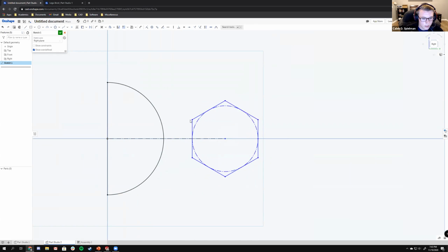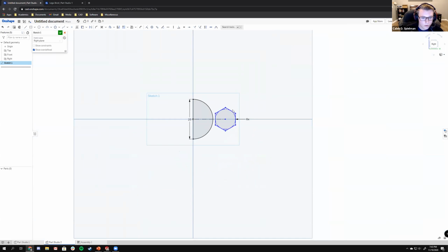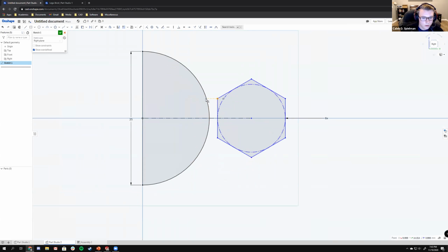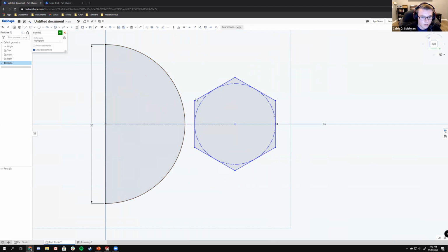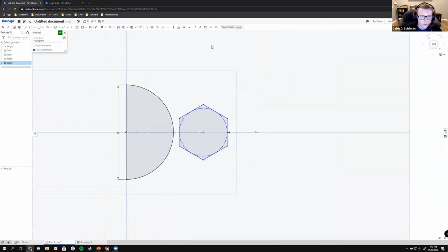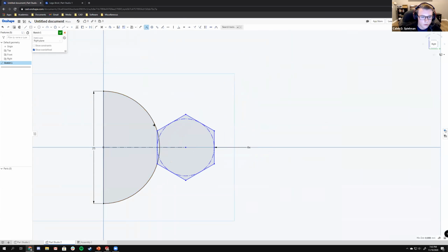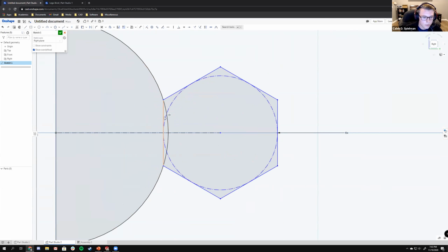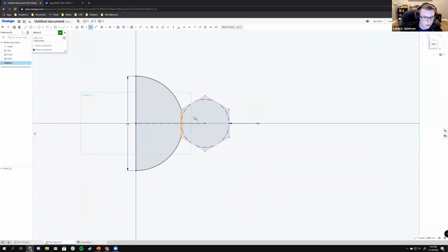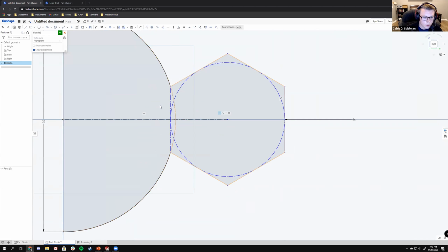Here, it is of course not defined, so let's begin by defining it. I want this polygon to be attached to this contour. But in order to do that, I need to make this point and this arc coincident. So I'm going to do that. Coincident. And this is by definition coincident, but just in case, I made it coincident anyway. Okay, so now I'm going to make this a construction line because I want this to be just one single contour.